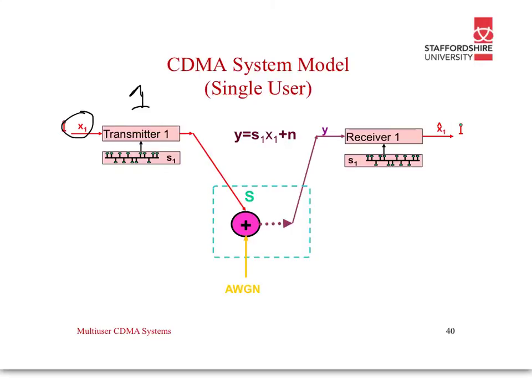The reason that we talk in 1s and 0s is because when we're implementing in hardware, we might be using logic. However, when we're transmitting across the channel, we'll be transmitting different voltage levels, so we can't transmit 0 volts, so we use bipolar, a 1 volt and a minus 1 volt. Sometimes 1 volt is represented by a 1 and minus 1 a 0.